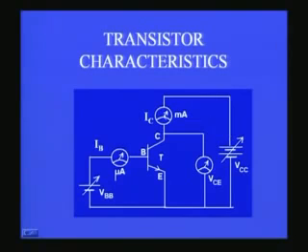So you vary the voltage by using a knob, starting from 0 in some specific steps, for example 0.5 volts or so, and then find out what the collector current is for each of these voltages, and also record the VCE.